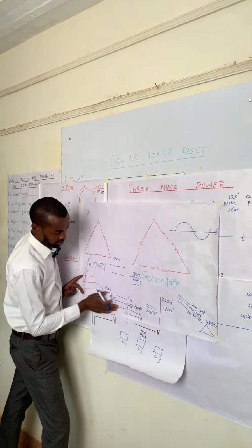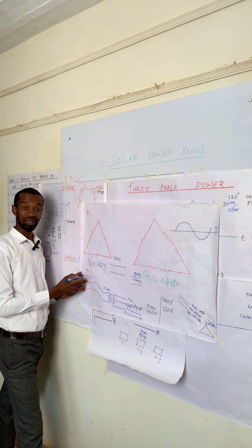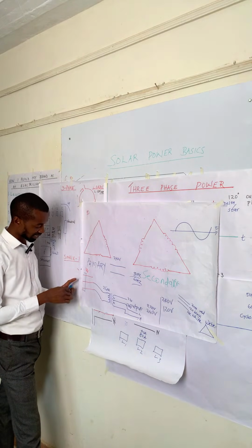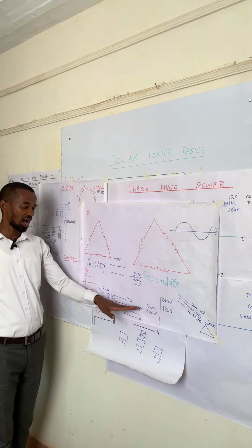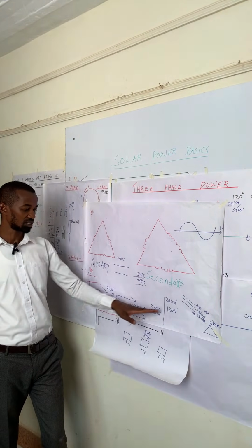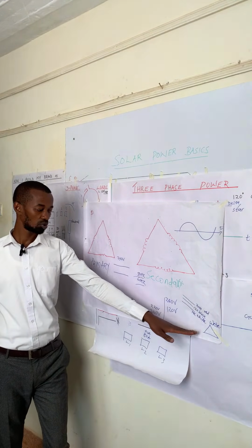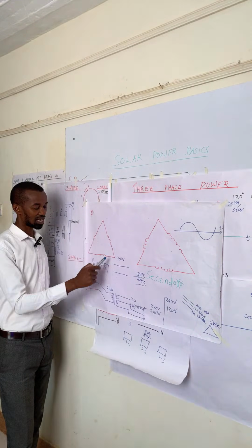And then this single phase transformer is at this point, but the customer is ahead of these other connections and ahead of this transformer. What will happen? They will need to make an application so that these conductors are connected from this point all the way here. If there are only single phase connections here, then it means that it will not be of help, because for a three-phase connection, remember we require a delta connection.